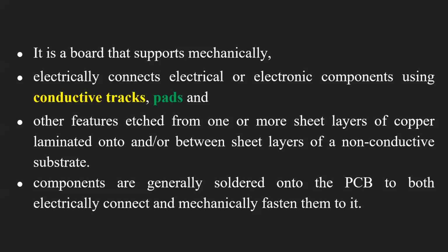So it is a board that supports mechanically and electrically the electric and electronic components using conductive tracks and pads, and the other features etched from one or more sheets of copper laminated onto and or between sheets layers of the non-conductive substrate. Components are generally soldered onto the PCB to both electrically connect and mechanically fasten them to it.